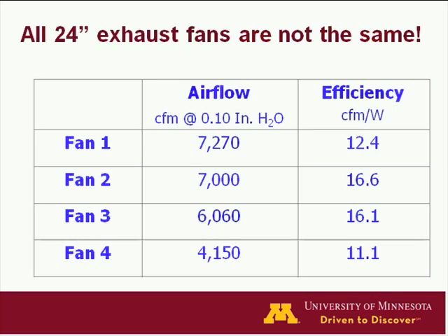So certainly when we select fans, airflow is very important. We need to select for getting the right airflow, but also you want to look at the efficiency. So you can see fans 1 and 2 have very similar airflow rates, but there are some differences in efficiency. Fan 2 is quite a bit more efficient, with a higher CFM per watt rating.